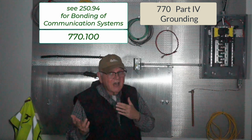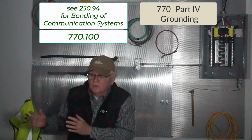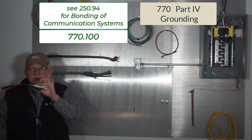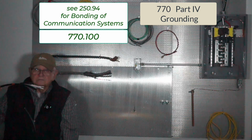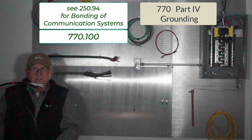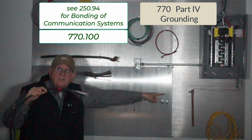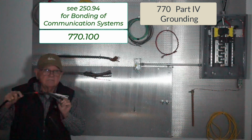But if it's not, if it's more than 20 feet away, then I have to what? Over here where I terminate my communication system wiring, I'm now going to have to drive a ground rod at that point. And I'm going to have to use a minimum 6 AWG conductor bonding jumper to run from this ground rod to the ground rod over at my service. So that's that 20-foot limitation.